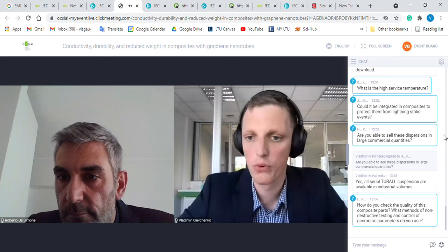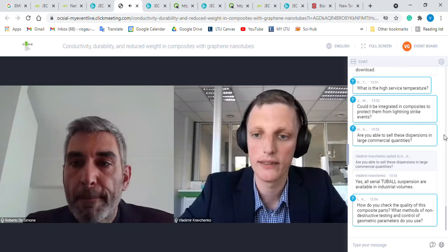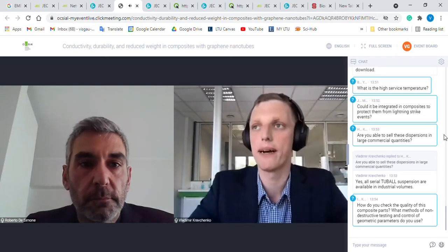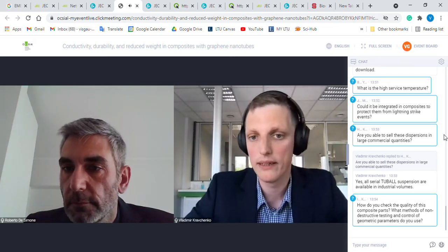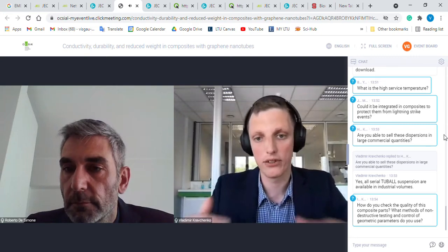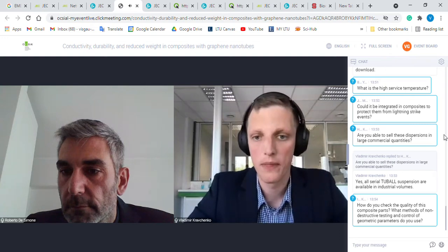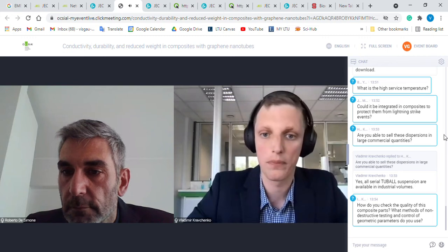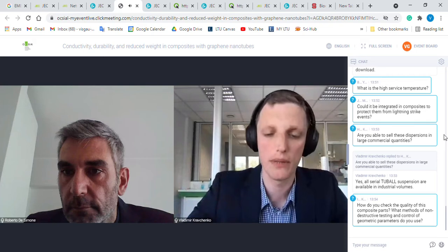So now let's go to the questions and answers we received in the chat. One of the questions was, could it be integrated in composites to protect them from lightning strike events? Yes, we had a few projects and commercial stories in this application in the past, but it will depend on many things. Is it a coating? Is it part of a layer, or is it in the composite? I think that in the thermoset area, one of our records was 0.02 ohm·centimeter, but it was a really thin coating with a very big dosage.